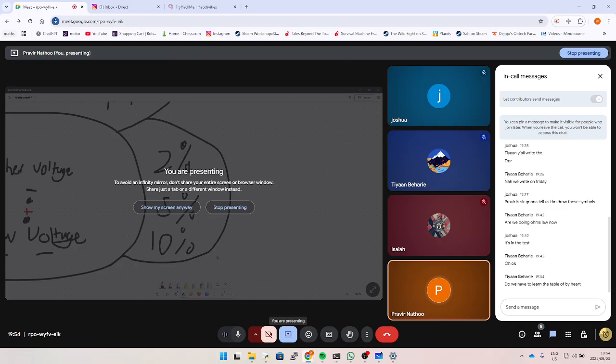An LDR converts light to resistance. We went over transistors. They're used in a switch. It's a digital switch, I explained that to you. LED we explained. The key thing to note with an LED is that it always needs to be wired with a resistor, because the current is too large in many circuits. For example, if you use a 9-volt battery, you need a 1000 ohm resistor to protect it, because the current flows too fast for an LED to handle it.